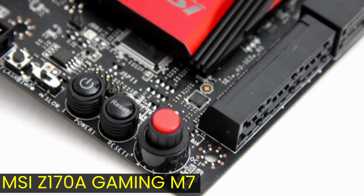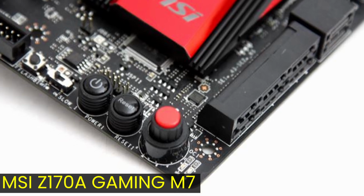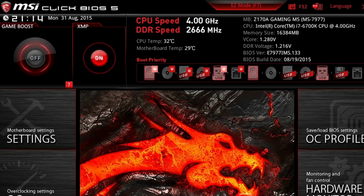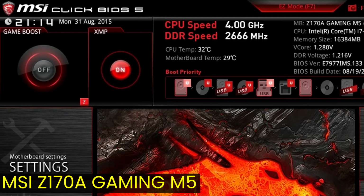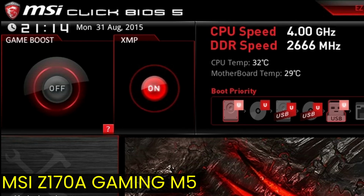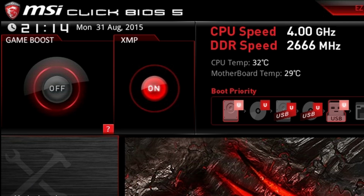The Z170 Game Boost knob is an 8-step dial that goes from 0 to 11. Each step has a predefined base clock frequency, CPU ratio, and voltage, which lifts the frequency of a Core i7-6700K from 4300 MHz at step 1 to 5000 MHz at step 11. The virtual BIOS version of Game Boost offered no multi-step approach, but a binary on-off for the Core i7-6700K. Game Boost On means running at 4.4 GHz, which is equal to Game Boost Step 2 on boards with the